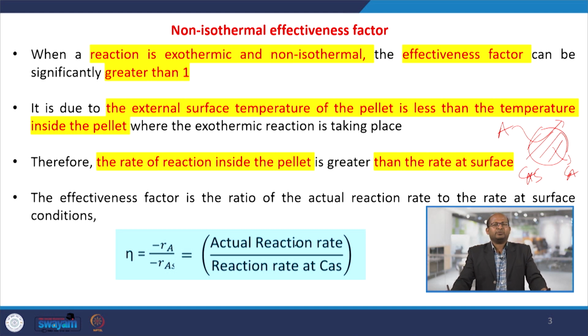So, we are considering a particular gas and solid reaction system. There the reaction may be exothermic or endothermic. Since the reactant concentrations at the surface and inside the pores are different, the rate of reaction would be different, and if any reaction is exothermic, then heat formation would be there. If we do not consider the diffusion, then the effectiveness factor of course would be 1. If we consider the diffusion, then the rate would be different at different locations since concentrations are different.